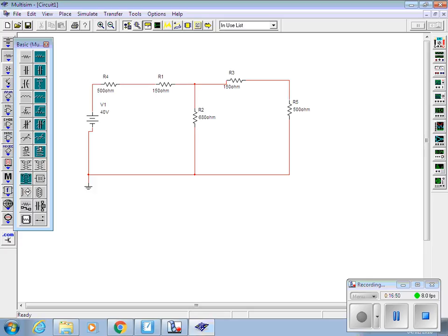Not here. We know that's 40 volts, but that's irrelevant. When we want to see what voltage we're getting out at the maximum 20 volts, we'll have that set to 40, but we should measure 20 here. It won't be quite that because of the mismatch we've got with the preferred values. But we'll finish that off next week. Alright? Yeah?